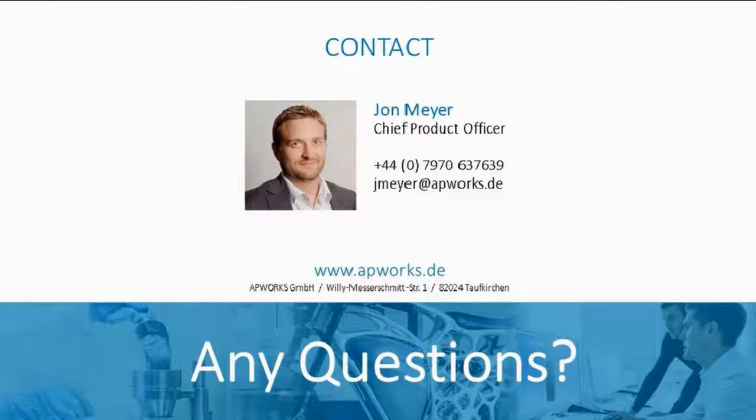If you talk about directed energy deposition, then parts many meters in length can be built, but they require some kind of finished machining all over. The biggest advantages there are around material waste, particularly for high value materials. So if you're interested in directed energy deposition technologies, Cranfield University have very good resources online in their WAAM-MAT. If you Google that, you should be able to find some really interesting reports and documents that will tell you more about directed energy deposition and what you can do on that large scale.